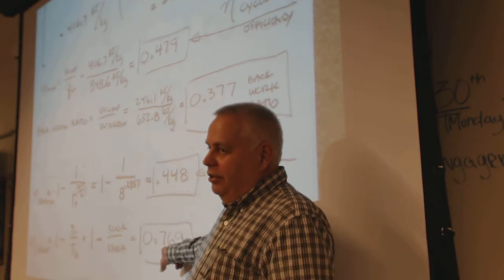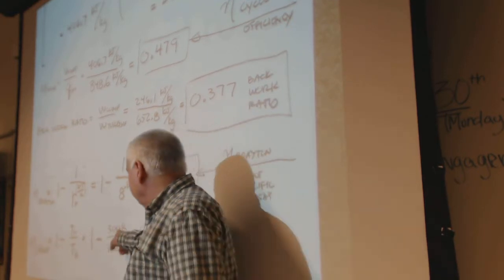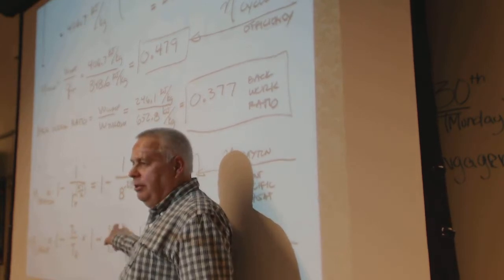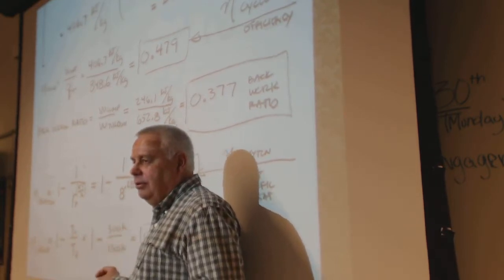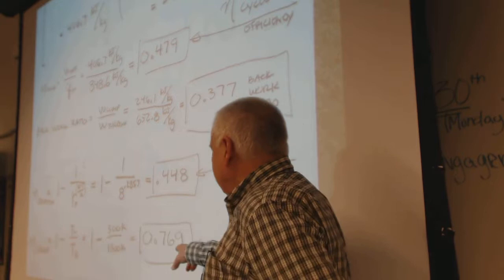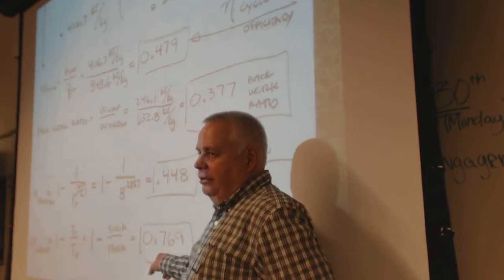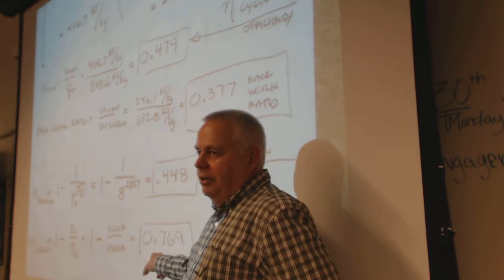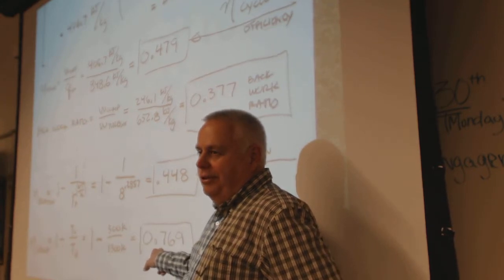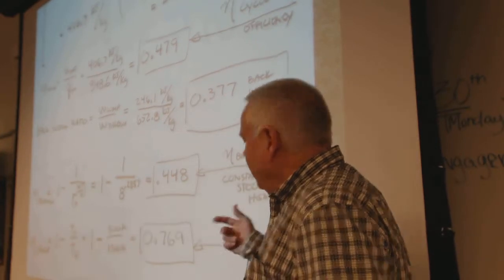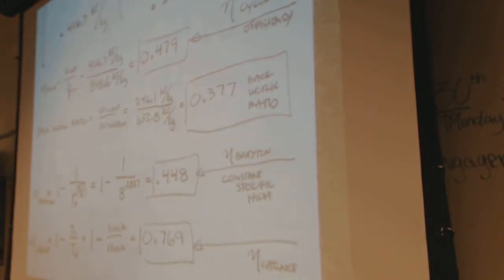Carnot efficiency uses absolute temperature; it doesn't have to be Kelvin, it could be Rankine, but it has to be absolute. That's a limit. If somebody says it's more than that value, then they're blowing smoke, or they don't know how to read, or who knows what it is. It doesn't get there. So that's the thing about the Brayton cycle.